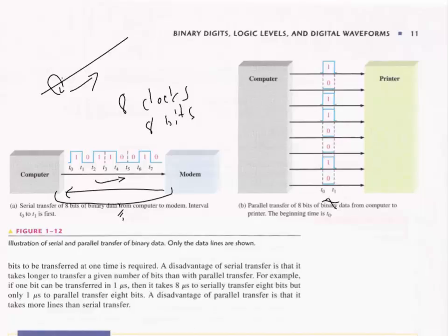If you have a constant DC current, there's no field set up around it. It has to be a changing current in order to induce the voltage. That's why you can't use transformers for DC voltages. That's why we have AC coming out of the wall.